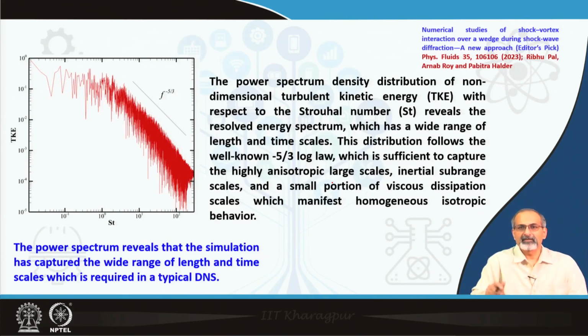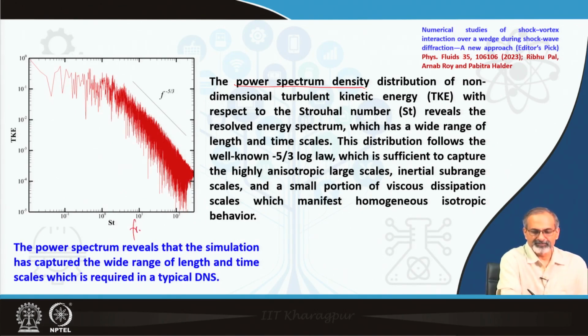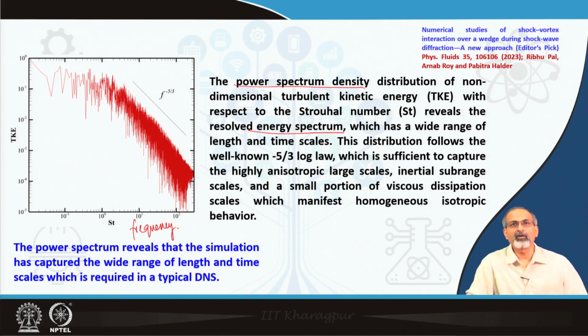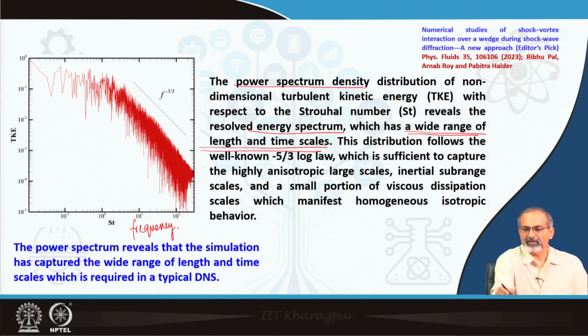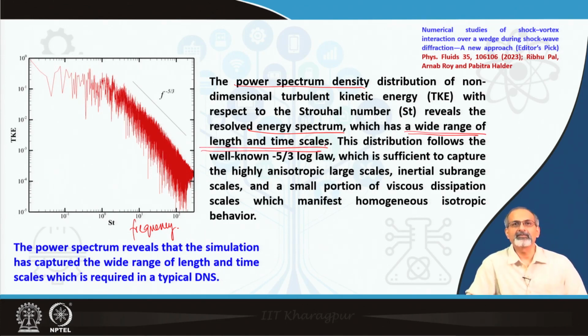We also need to check the so-called power spectrum density distribution of non-dimensional turbulent kinetic energy with respect to the Strouhal number, or essentially the frequency, to show how far the energy spectrum has been resolved. That is essential to make sure that the wide range of length and time scales which show up in such a complex flow field is well captured.